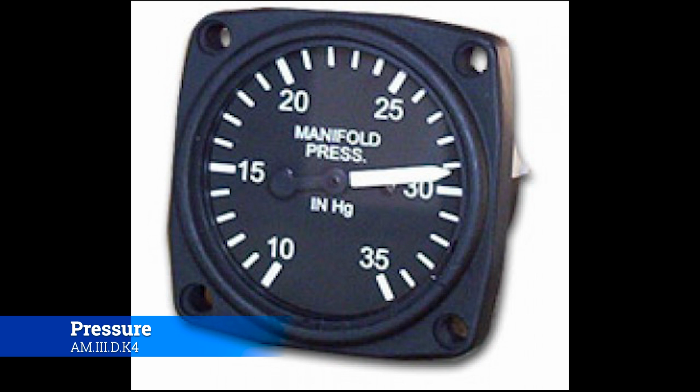So you're going to set the prop lever to where you get the right manifold pressure. That means the engine is turning at a certain RPM, and you want to load and deload the engine so that it speeds up or slows down, so that you get the right level of pressure inside of that intake manifold, so that you can continue to make the same level of power that you want to make. Now, this particular gauge is corrected for temperature and altitude internally, so you don't have to worry about any of that. You simply set the manifold pressure, and off you go.